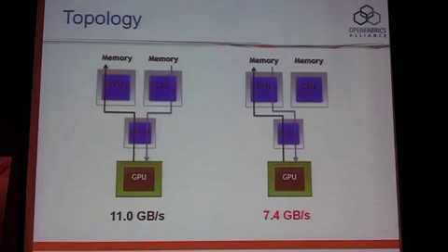And what I've labeled as chipset is really the PCI to memory fabric bridge. So it's PCI on one side, it's either HyperTransport or QPI on the other side. On the left, you see the bisectional bandwidth for a bidirectional transfer, meaning we get about 11 gigabytes per second, adding both write to host memory and read from host memory, if we are writing to memory that's controlled by one of the CPUs and reading from memory that is controlled by another CPU.